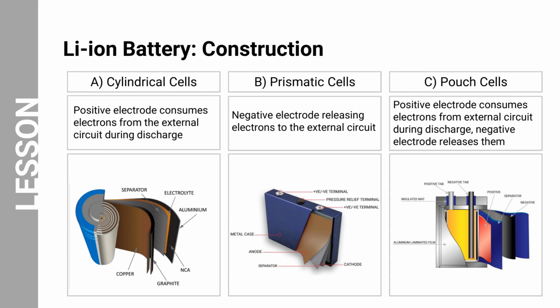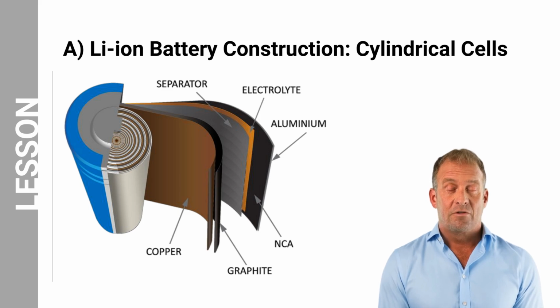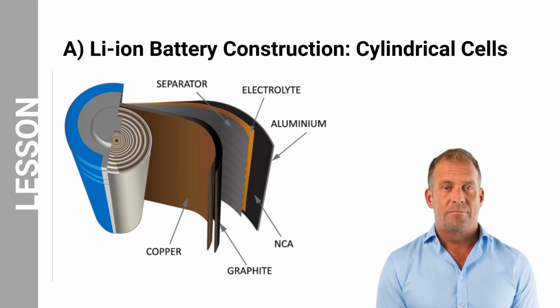The cylindrical battery design shape resembles a traditional D cell with a steel can. The prismatic battery design shape resembles a rectangular or box-like design. The pouch battery design is a flat rectangular shape. This shape is distinct from cylindrical or prismatic cells, which have a more rigid and defined structure. For the construction of the cylindrical shape, the active materials are processed into long ribbons and wound in a spiral inside the cylindrical case.